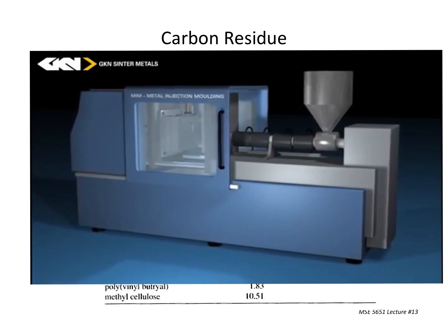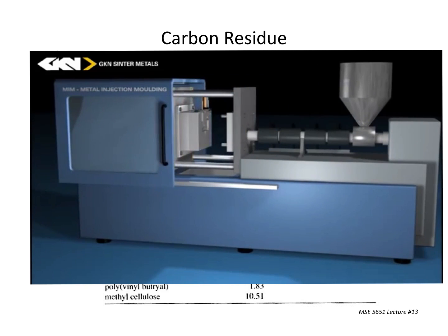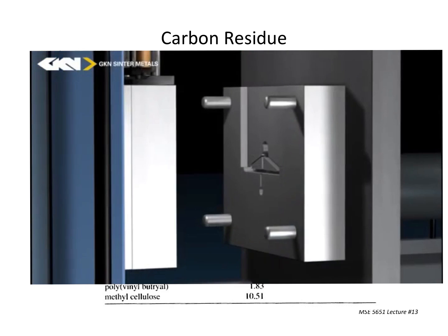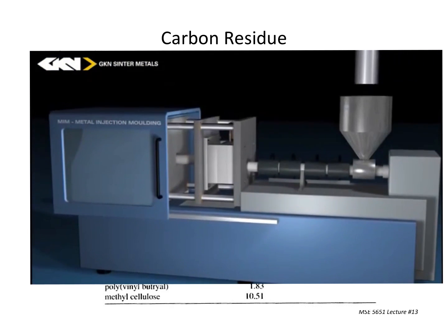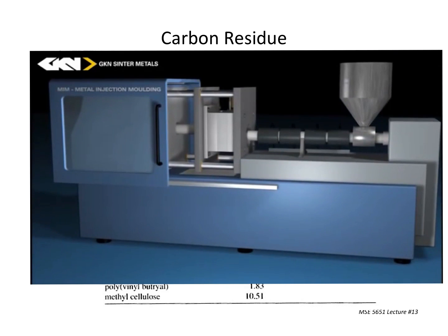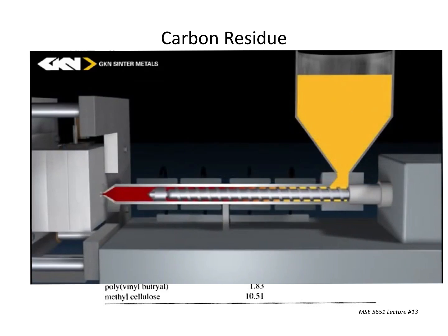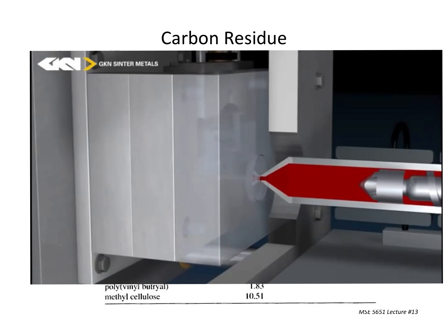And so we have the injection molder itself, which we talked about now, in which those platens are located. And so we're going to utilize that type of structure, and we have these pins holding everything together, also help take it apart. And so we bring in all that pre-mixed organic multi-binder component. We go through the extrusion process, which is mostly friction to heat this up and turn that into a continuous fluid pool of material. So it goes from being lots of trapped air to being 0 trapped air when that final fluid is ready for injection.